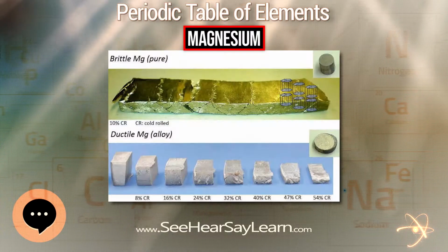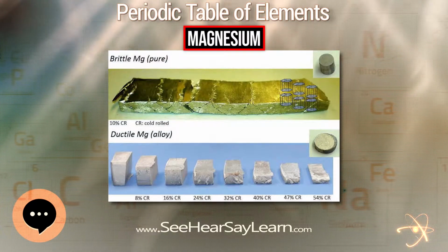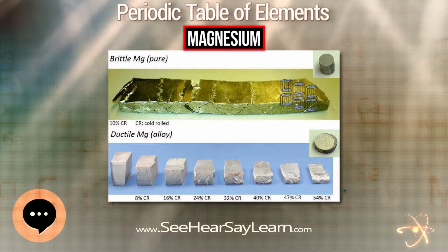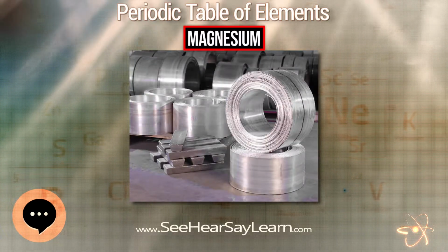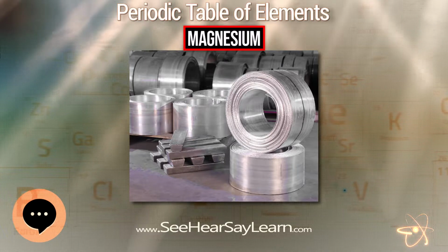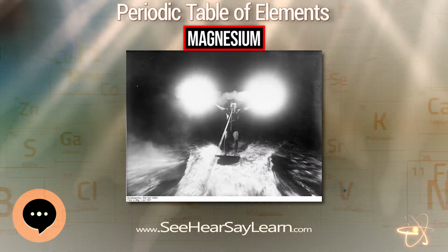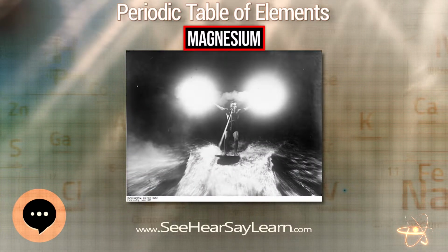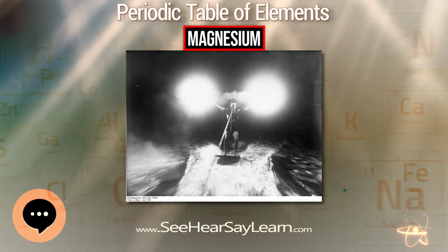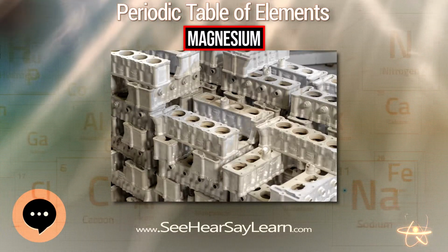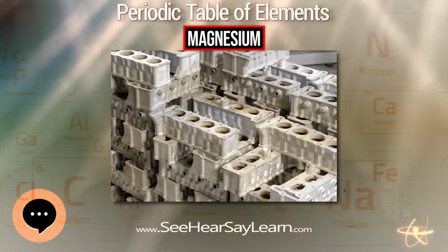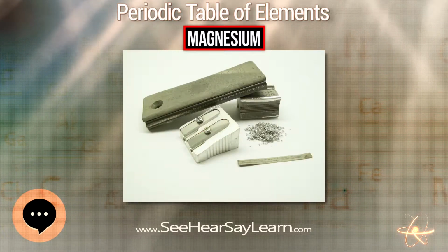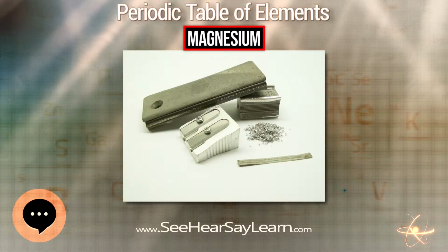Magnesium metal and its alloys can be explosive hazards. They are highly flammable in their pure form when molten or in powder or ribbon form. Burning or molten magnesium reacts violently with water. When working with powdered magnesium, safety glasses with eye protection and UV filters are employed because burning magnesium produces ultraviolet light that can permanently damage the retina of a human eye.